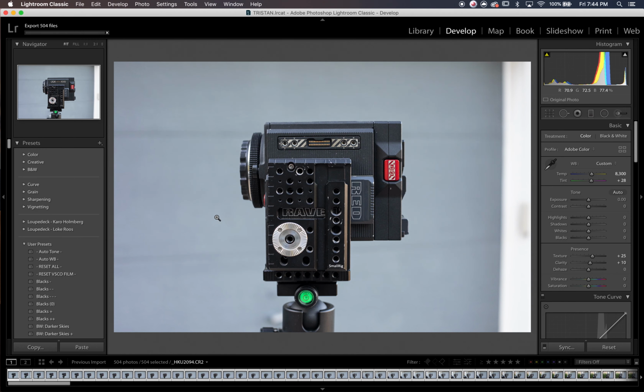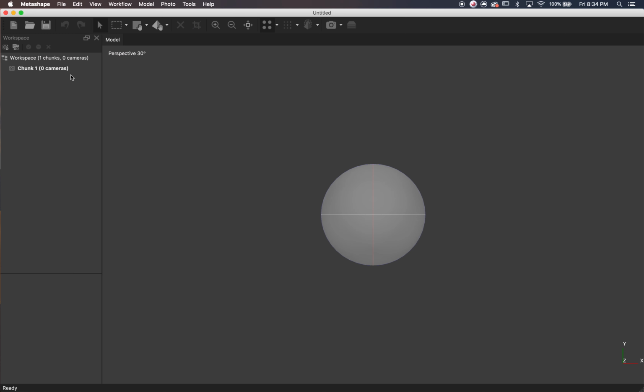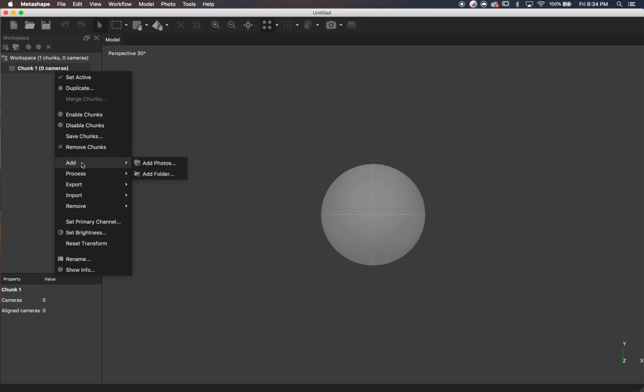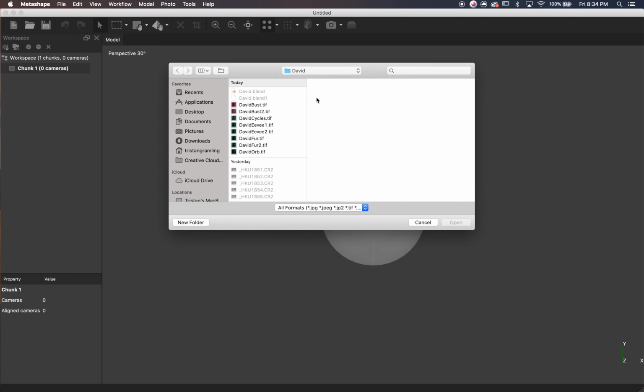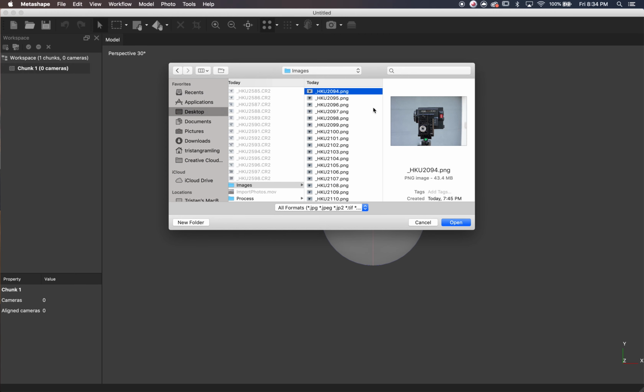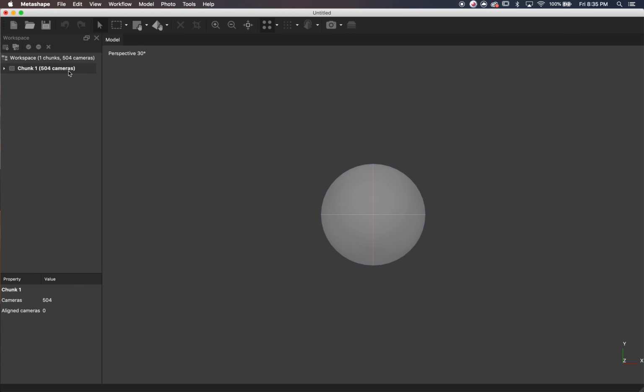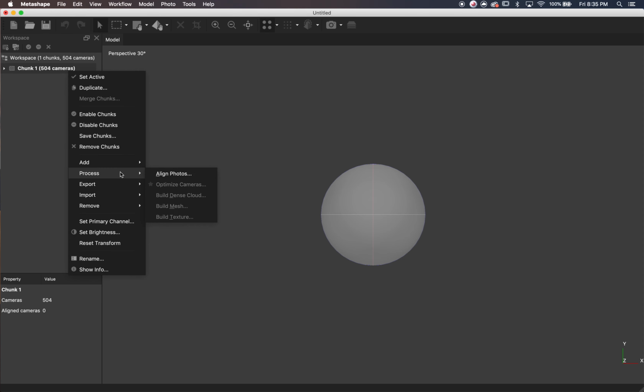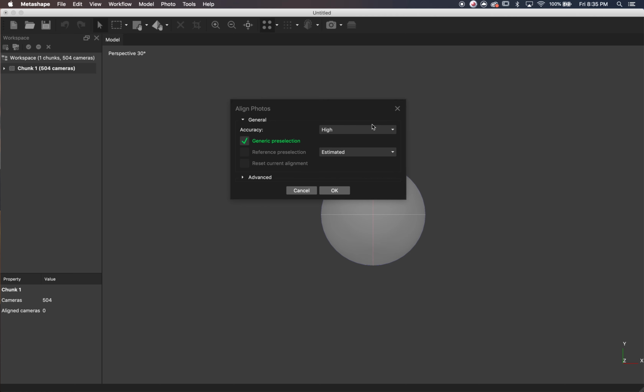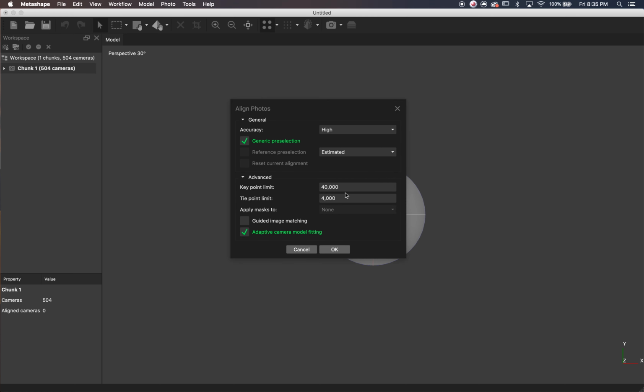The program that I'm using is called Metashape. I'm just using a free 30-day trial, and it's pretty intuitive to use here. So the first thing I do is import all of the photos and then go over to this chunk and align the photos. I don't think I actually showed it in this video, but there's a little camera icon in that top bar on the far right. You can click that and actually see where the photos are mapped, and it's actually really cool.